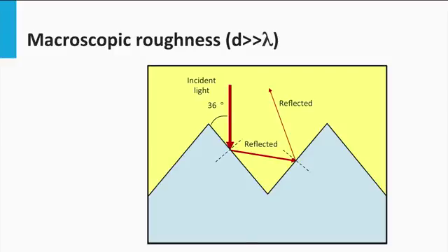Here the light can still be coupled into the silicon. Secondly, the scattering at textured surfaces will couple the light at angles into the wafer. This means that the absorption path length will be enhanced. This certainly enhances the absorption of light with a wavelength above 900 nanometers.